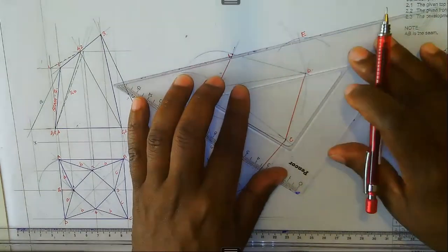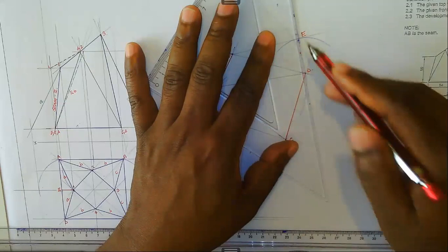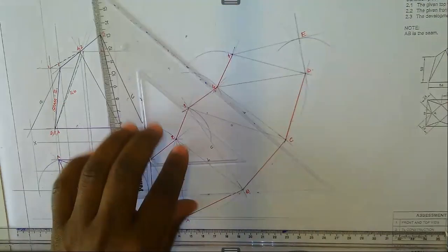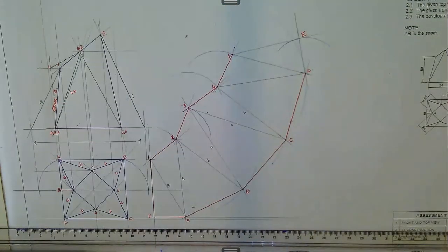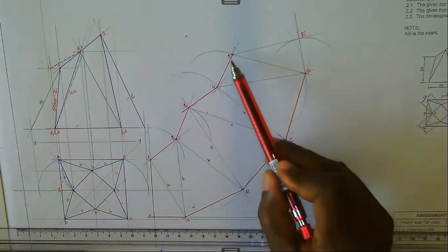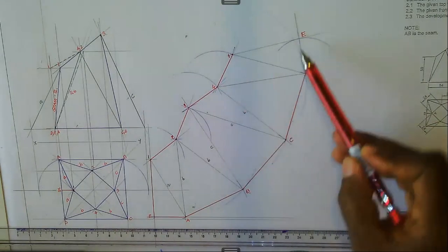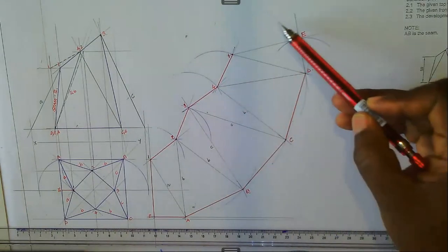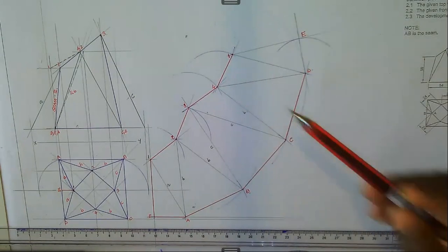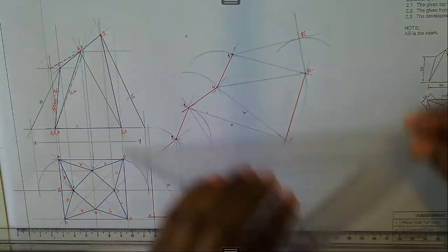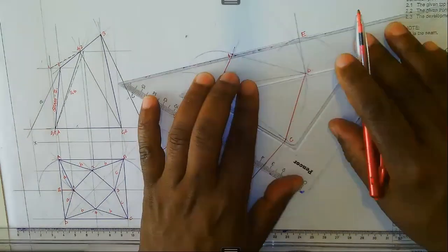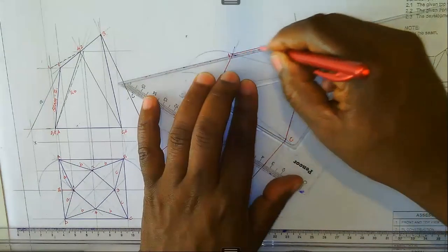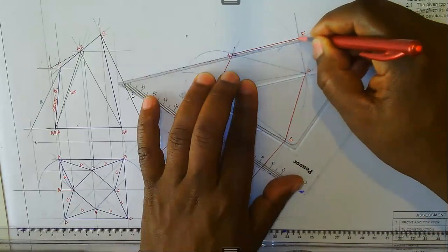So connect. As you can see, we are also going to create an angle of 90 degrees. Right. One indicator that would show you whether you are right in terms of the angle, especially if you are defining an angle of 90 degrees: this line should be tangential to that, and this line should be tangential to the arc, which is like that. If you find something like that, you know that your constructions are okay. So I'm going to outline here. And also do the same.